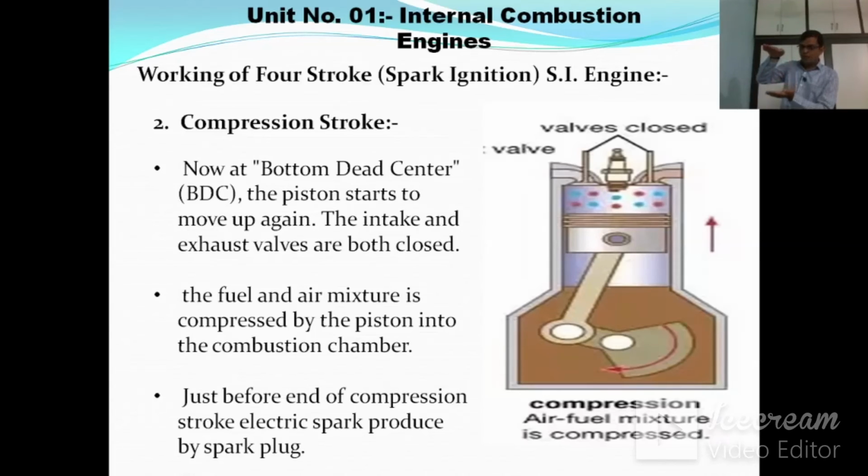When the piston moves from bottom to top dead center, both valves, the suction and exhaust valves, are closed. As the piston moves upward, the fresh charge is compressed. At the end of the compression stroke, the spark plug produces the spark and the charge gets burned.